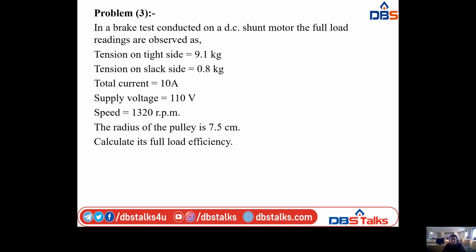Okay, and motor input current, that is IL, they already given 25 amperes. So just now we calculated the stray loss, that is 726.31 watts, and next we have to calculate the shunt current. You know the formula to calculate the shunt current for the shunt motor, ISH is equal to V by RSH. Here V they already given 250, by RSH is 200, that is shunt field resistance, and finally we have the shunt current 1.25 amperes.